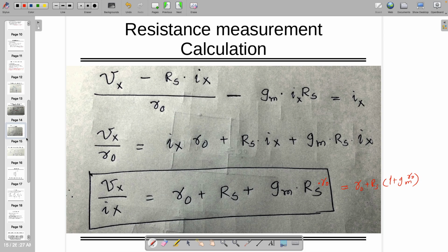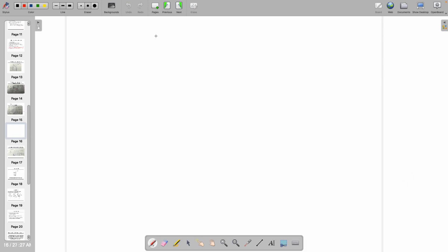So the final answer which we got is as follows. If there is a circuit which looks like this one, no matter what voltage you are giving, looking from here, this will go to ground, whether it's Vin or Vbias. I don't care about this voltage. I only care that M1 has to be in saturation.